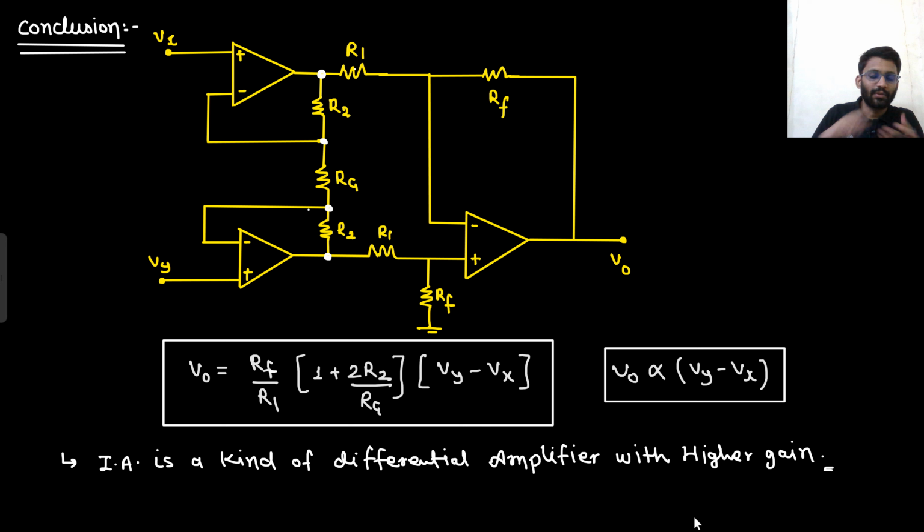Say yes or no. So there is no issue of changing other resistances. Are you getting this point? Or I can decrease my Rg value. If I need to increase the gain, I can simply decrease my Rg value by only controlling one resistance. This resistance is generally controllable. So by reducing the value of Rg, I am increasing my gain. So there is more control over the gain.